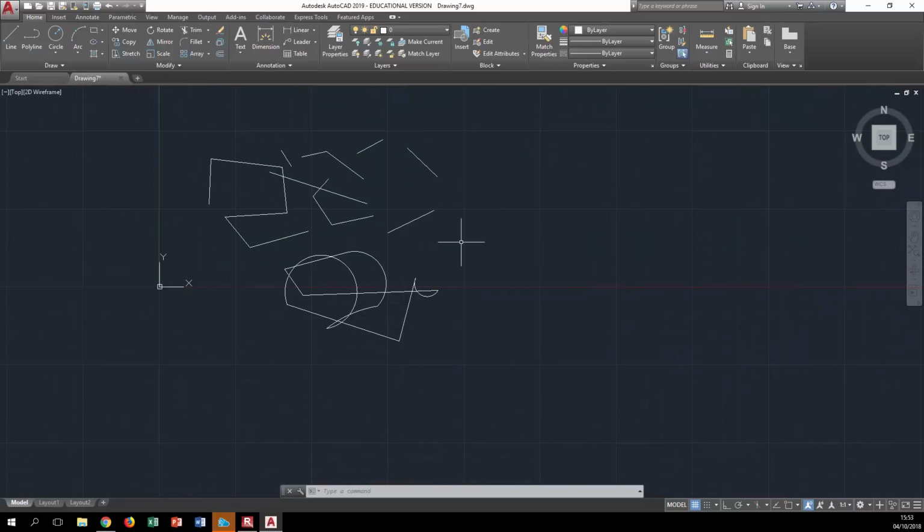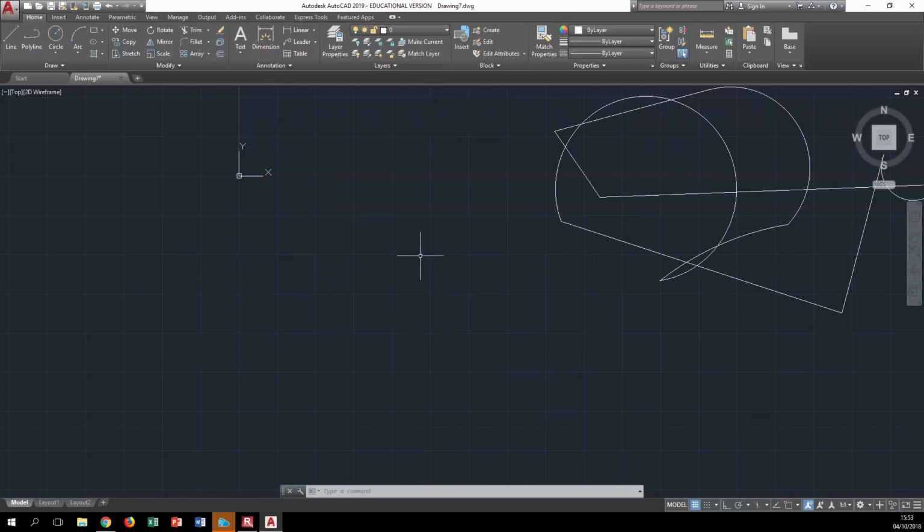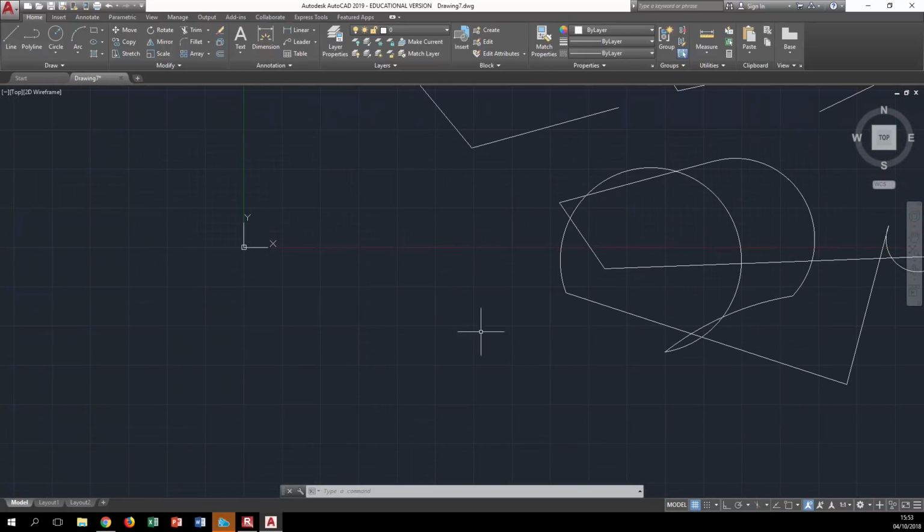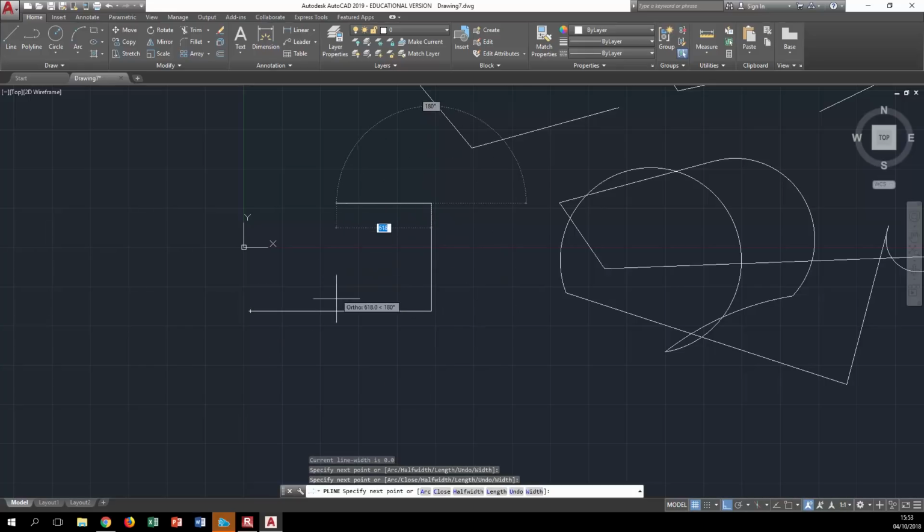So it's the pen, and you can zoom in and out also from the wheel. If I want to do vertical and horizontal perpendicular lines, you can just use the ortho mode. So ortho mode restricts the cursor movement to either vertically or horizontally. So I'm clicking on it, and now I'm trying to draw, and you will see that the movement is restricted.